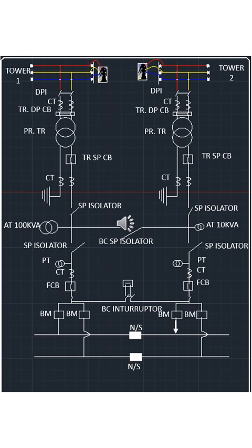And the source is the generating station. Though generation is at a comparatively low voltage, around 6.6 kV, 11 kV, 13 kV, for transmitting power at low voltage the conductors will have to be thicker due to high current, because our traction load is drawing huge current.